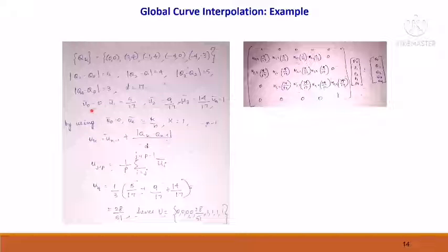We will add everything to get the value of d. So we will find its knot vectors over here. These knot vectors are calculated by this distance divided by the total distance. So these are the average distances, that is, the averaging knot vector is calculated over here. By using these formulas, that is, u naught is equal to 0 and uk is equal to k by n, we calculate the total averaging knot.